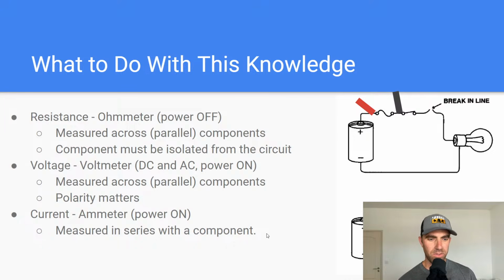One thing to note is that this can sometimes be dangerous if the current is high enough. So you want to make sure that you're not touching bare wires, and this can also open you up to damage to your multimeter. So I wanted to throw that out there as well. Different multimeters will be rated for different amounts of current, so it's another thing to keep in mind.